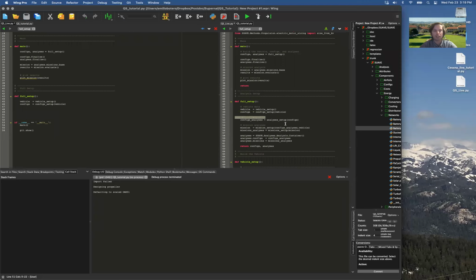Next, we'll set up the analyses. So the analyses, this is where we will specify the aero model that we want to use. Now, the aero model used for this drone is very different than the aero model that we use for full-scale aircraft, for manned aircraft. It's for low Reynolds number, and specifically for transitioning vehicles that have flat, high angles of attack. So I'll discuss that when that comes in a little more detail.